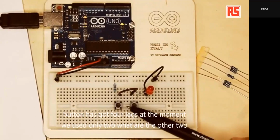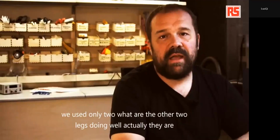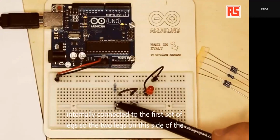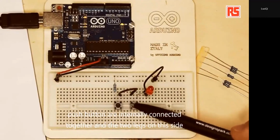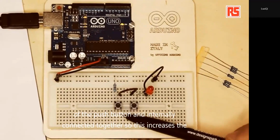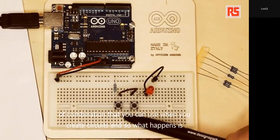At the moment we used only 2. What are the other 2 legs doing? Well, actually, they are internally connected to the first set of legs. So the 2 legs on this side of the push button are internally connected together, and the 2 legs on this side of the push button are internally connected together. So this increases the number of combinations that you can use when you create circuits.